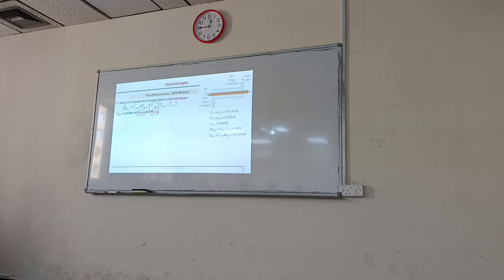As an example, here he is showing the hot oil entering at this temperature, with flow rate and CP, similarly cold water with temperature, flow rate and CP. So here I can define C minimum because the MCP product of cold fluid and of hot fluid are given. Here the hot fluid has the lower value, so it is C minimum.